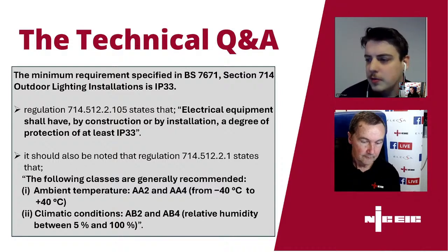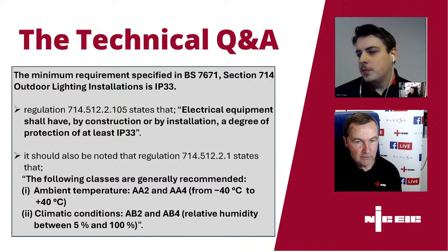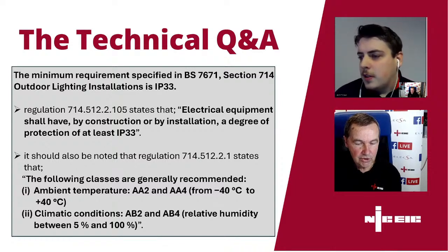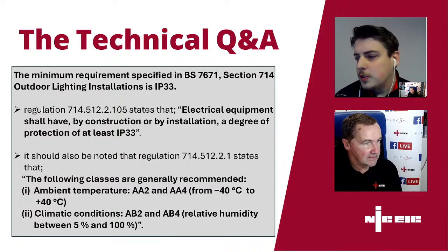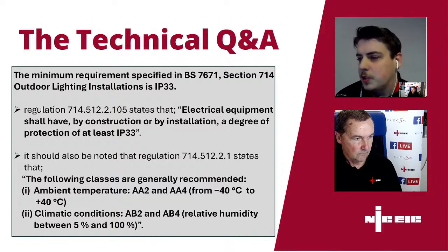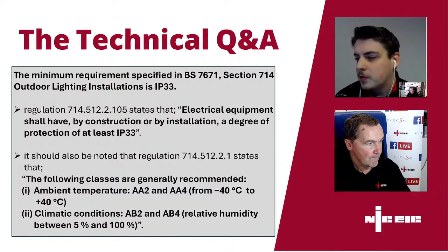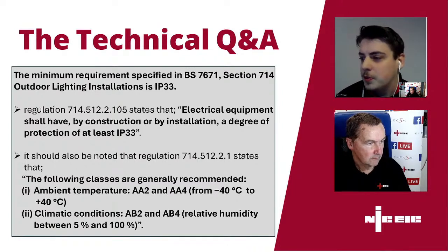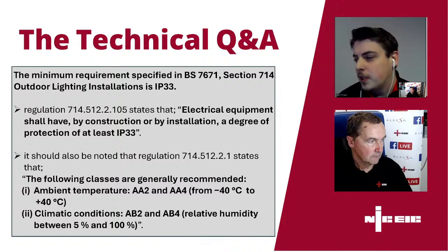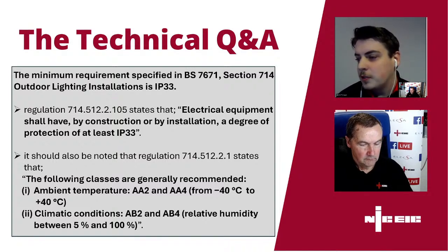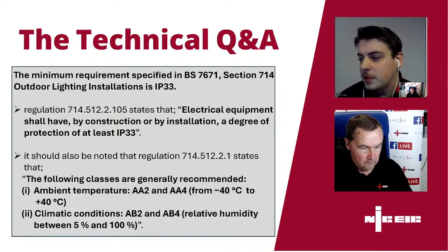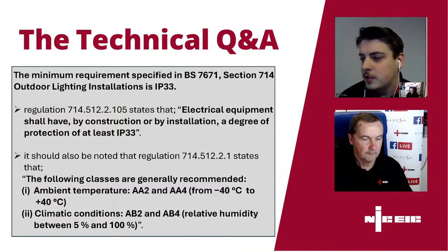1.45 on the insulation part of the rag. Can you just read us what it says? Yeah, James, sure. Question 1.5: do clipping blanks fitted in a DB or consumer unit comply with the requirements of 7671 with regards to access to live parts? The answer is yes, provided that the distribution board or consumer unit conforms to BS EN 61439 and is fitted with blanks that are firmly secured in place with sufficient stability and durability to maintain the required degrees of protection and appropriate separation from live parts under normal service conditions.